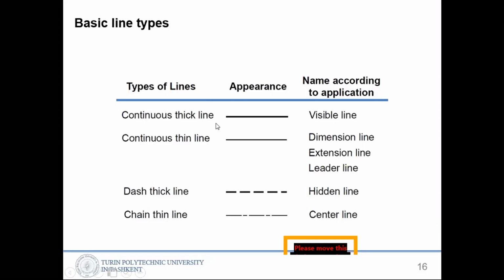Okay, so the line types are very important because, for example, a continuous thick line means there is an edge. You have to draw an edge using a thick, continuous line. A continuous thin line you use to represent dimension lines, extension lines, and leader lines. The next lectures will include how to draw those correctly. For now, just know that if you draw a thin line to represent the edges, that will be wrong. You have to use a thick line to represent an edge of the part.